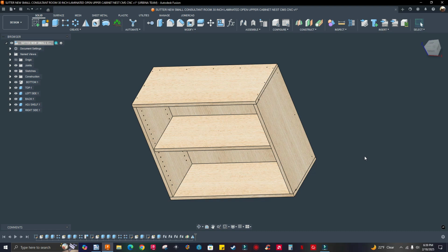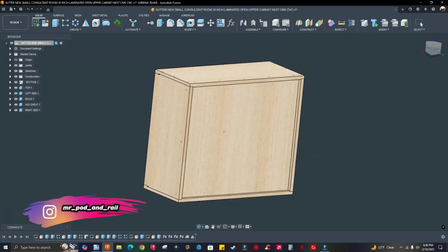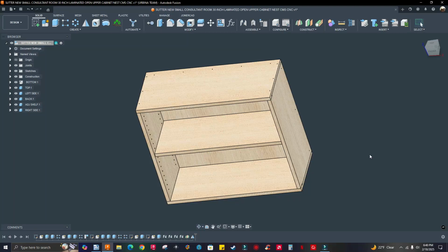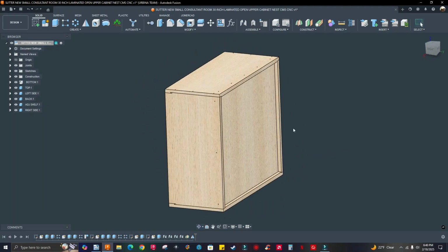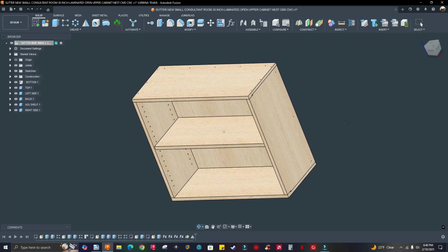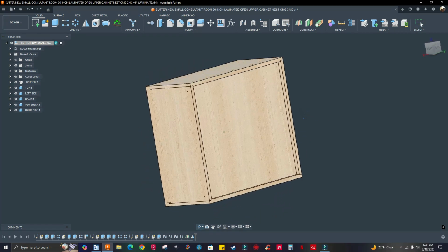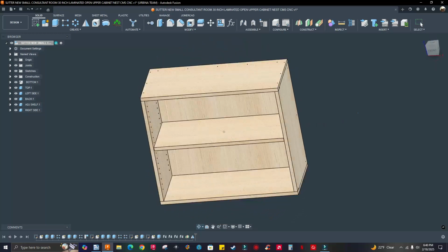That's because I don't really cut the doors out of the sheet. They actually get cut on the beam saw, which is faster. So when I'm making these parts on the CNC machine, the doors are being cut on the beam saw. It just reduces production time.